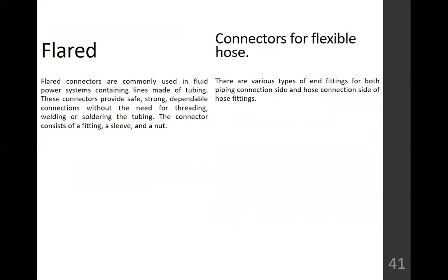Third, for those with flaring tools. Flared connectors are commonly used in fluid power systems containing lines made of tubing. This connector provides a safe, strong, dependable connection without the need for threading, welding, or soldering the tubing. The connector consists of a fitting, a sleeve, and a nut.